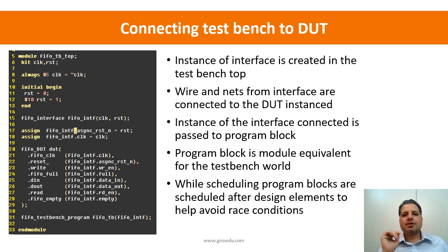And now let's see. Here we are creating, again, a test bench top. It's a module, and doesn't have any ports. Test bench top is a container for your DUT as well as your test bench, and the connection between the DUT and test bench. Those are the 3 things that we will be doing in the test bench top. So we have instanced this DUT, and now if you compare to the previous slide, instead of connecting to the individual wires, I am connecting them to the wires, or the variables, present inside the interface.